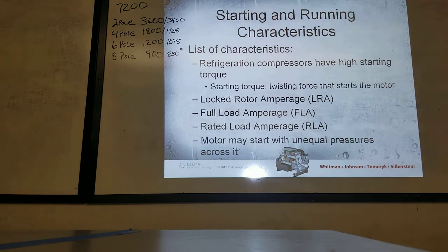Starting and running characteristics. Refrigeration compressors have high starting torque. Starting torque is the twist force that starts the motor. Locked rotor amperage, LRA. Full load amperage, FLA. Rated load amperage, RLA. The motor may start with unequal pressures across it.